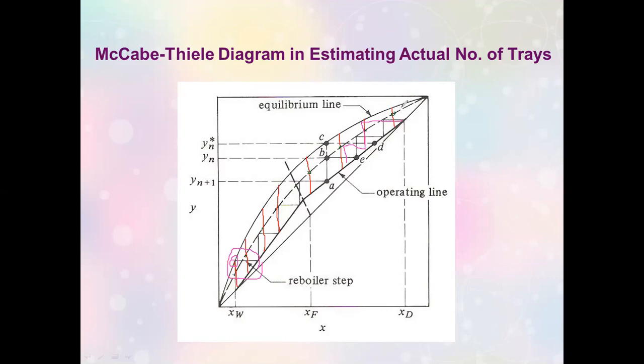Question. So, it is important to understand the drawing of the line. You measure the length of the line that you have drawn from the operating line to the curve, or from the curve to the operating line. It's the same length anyhow. But what is important is that from the operating line to that point where your new curve should be drawn, that should be your Murphree efficiency.